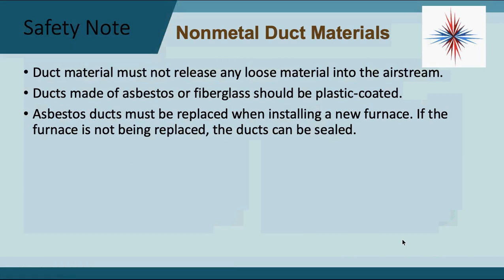Duct material cannot release any loose material into the airstream. Again, see my notes on the fiberglass ductwork. Ducts made of asbestos. Well, I don't even want to see asbestos in ductwork anymore. This is old. But fiberglass should be plastic coated. Remember, asbestos is fine as long as you don't disturb it.